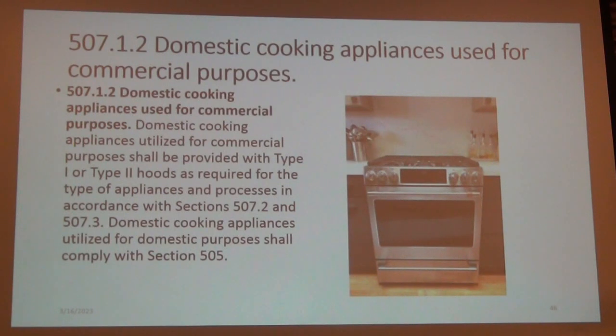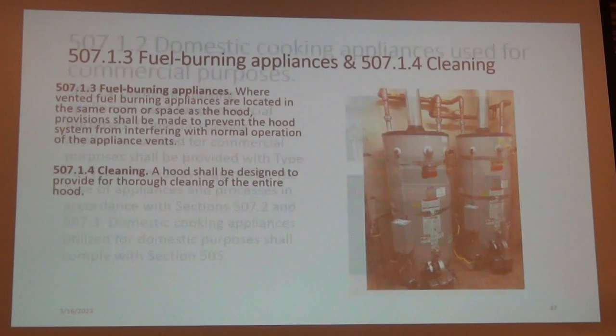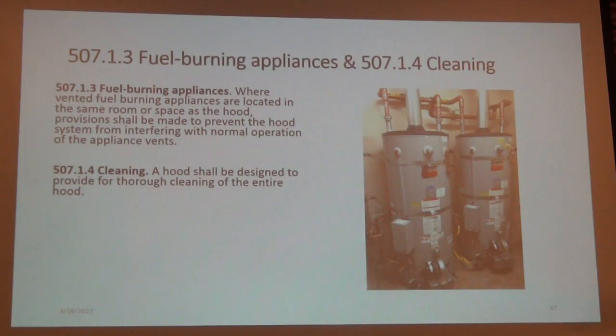I beg to differ with you. Well, that's not the way I'm reading it, because it says in chapter 3 that the appliance must be installed according to its listing. The listing will say residential or commercial use only. On the appliance itself, the manufacturer will tell you it's prohibited to be used for commercial. Plus, most of those residential ones do not meet NSF standards, and the health department would not allow it. Fuel fired appliance, same thing here.